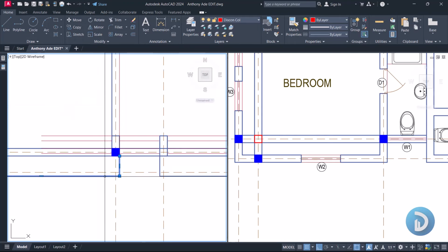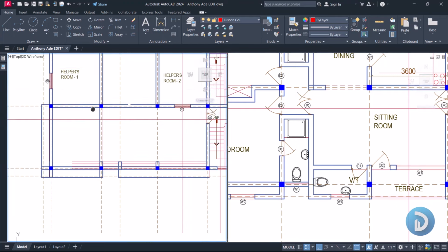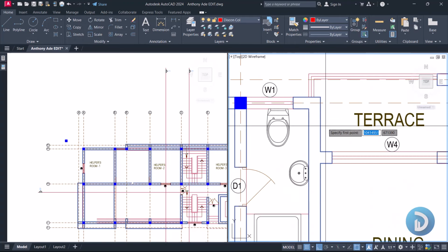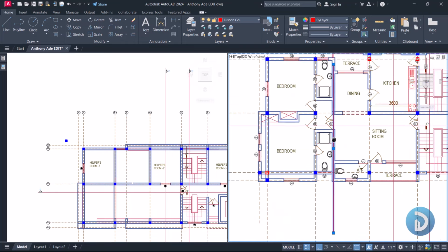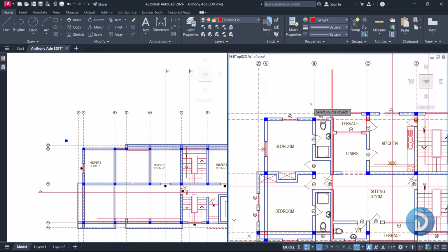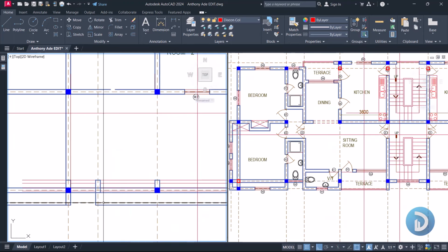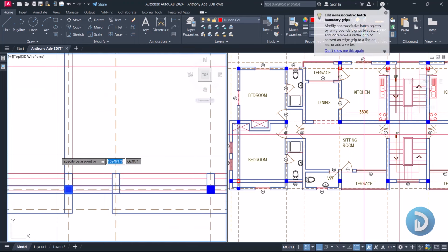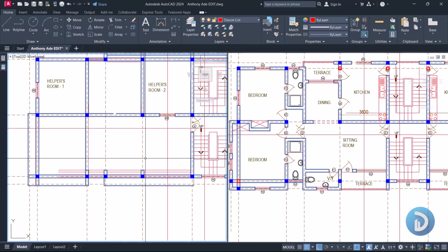So we'll extend this to this. Okay, and our next point of contact should be grid line B asterisk. Okay, so let's recreate this grid line on this first floor layout. Let's create this. Yeah, we'll drag this up, we'll match this with this. Okay, so this should be our next point of contact, and due to the cantilever at this part as well, we'll create a copy of this column to this part, so it will support this cantilever coming here.